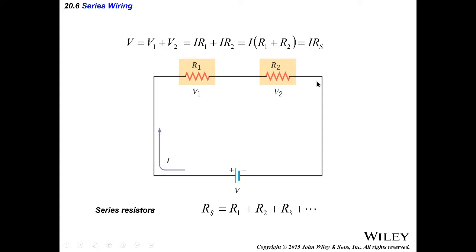Why not? I guess because if one of them blows up, all the others can still work. If you don't want it to be series, if one of them breaks, then that means all of them are not lit up also. That makes sense.